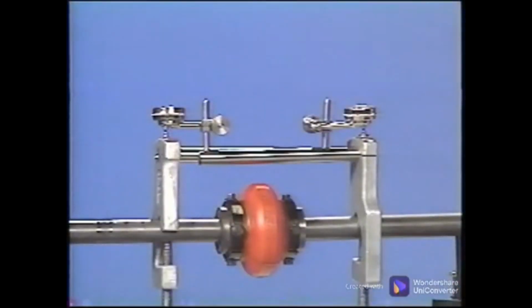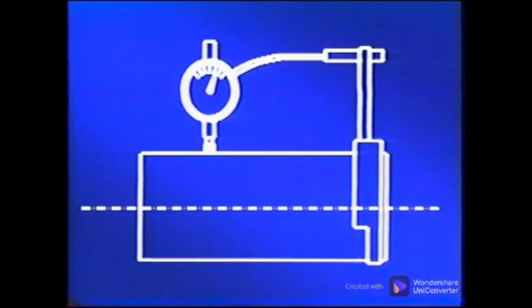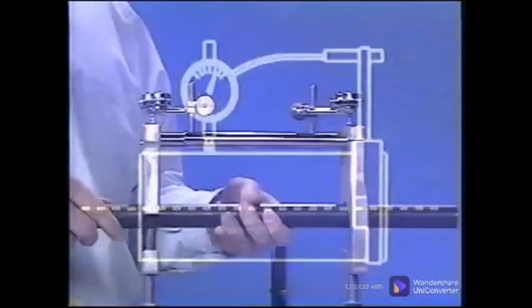One consideration that is often overlooked in the alignment process is bar sag. Anytime dial indicators are used for the alignment process, there will be some amount of deflection of the bar due to gravitational force. When the shaft is rotated, the bar sag varies and must be measured and accounted for in the alignment process, or all the calculations will be in error.